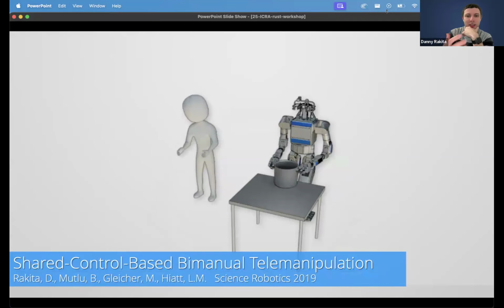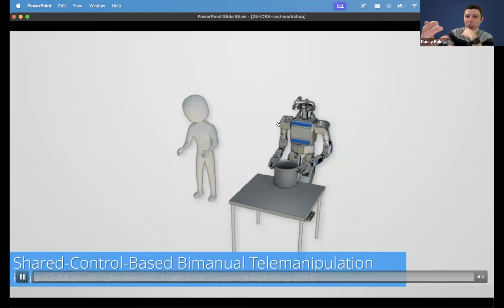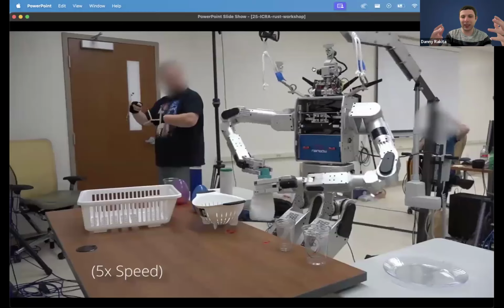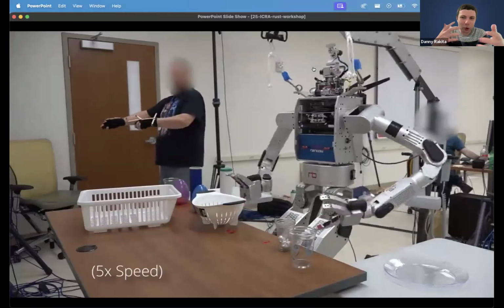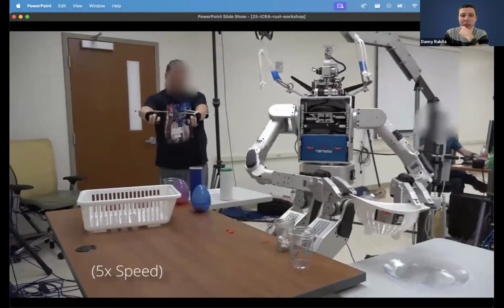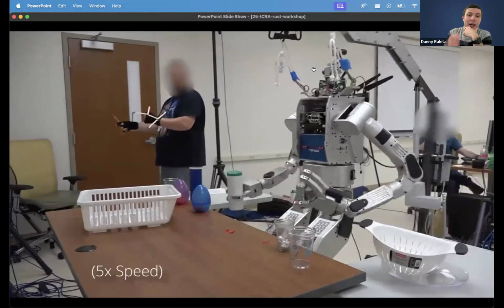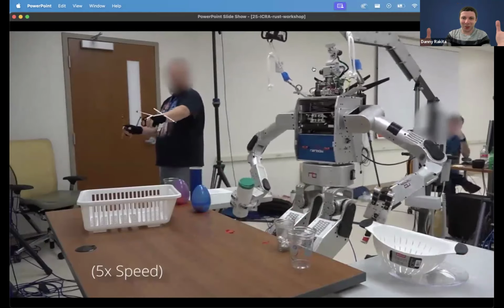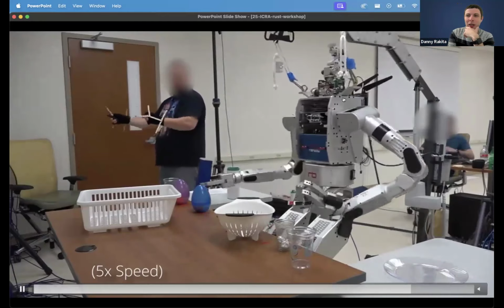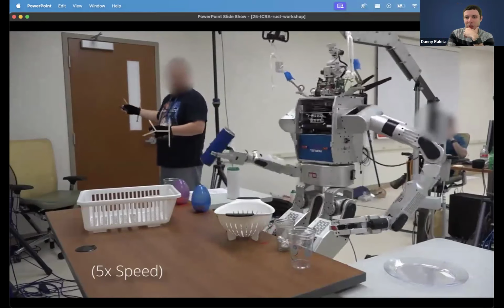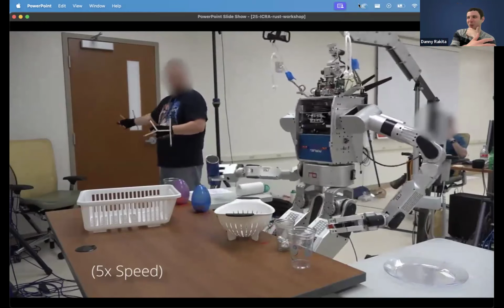Essentially the following summer, I was working at an internship at the Naval Research Lab in DC, and we wanted to apply this on bimanual robots for this bimanual control problem. Our result looked like this. There are some cool inference steps going on in the background to recognize bimanual actions that are happening in real time and fill the gaps in. But the thing to focus on here is that all the motion at the end of the day is being driven by RelaxIK, at the time purely in Python, and this bimanual robot is a 15 degree of freedom system. This is more on the 30 hertz side of the range, and over half the summer I spent trying to figure out filtering algorithms, just ways of overcoming this very slow optimization solver.